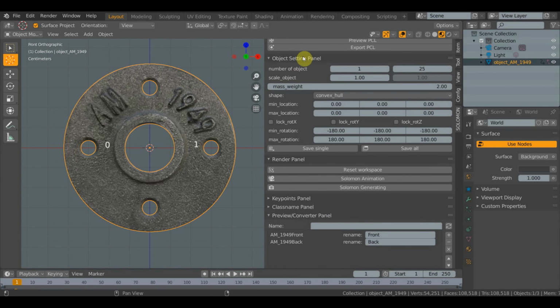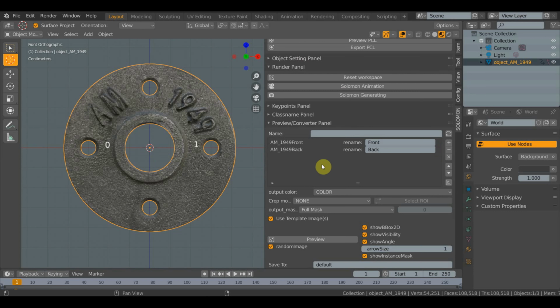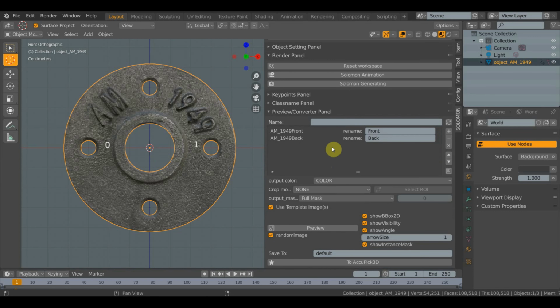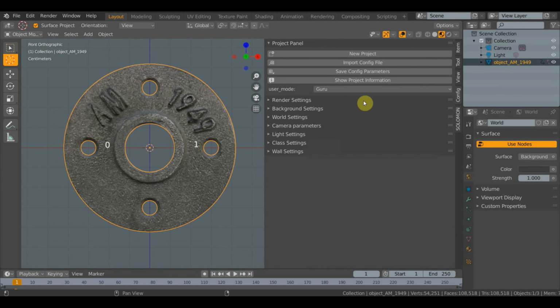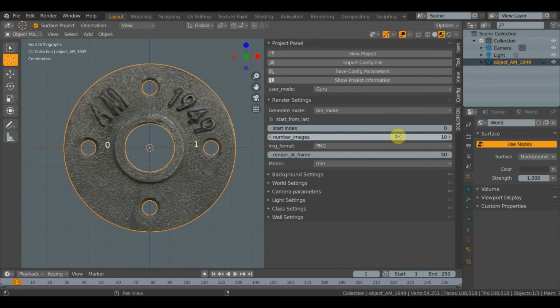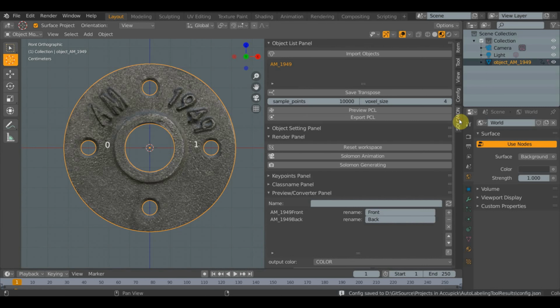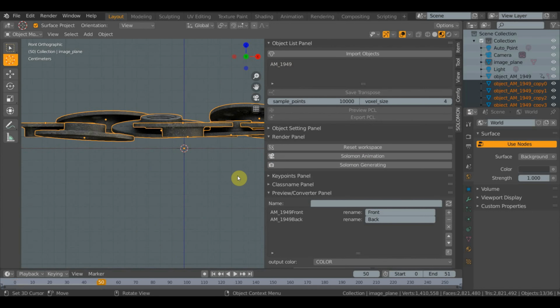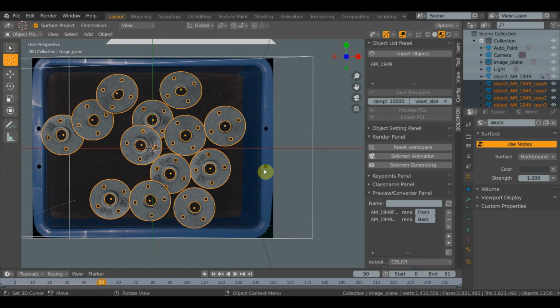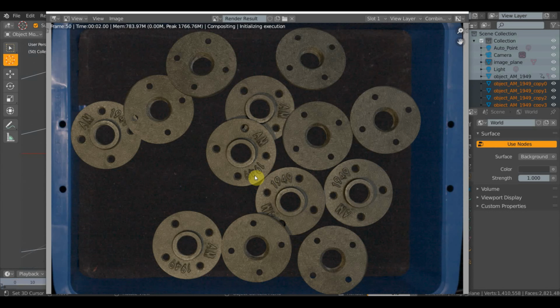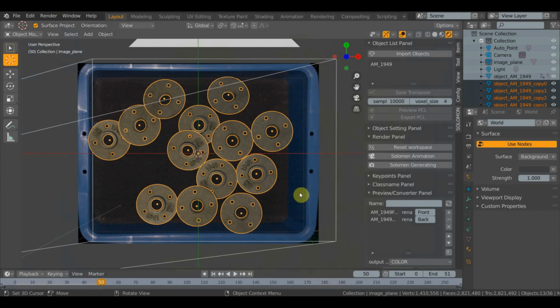Due to this being the first set of images we are going to create, I strongly suggest you start generating a small quantity of images with the objective to evaluate that the results are correct. That is why I am going to generate 10 images only. Also, don't forget to save the modifications recently applied to the project, and let's briefly check with one more simulation that the parameters recently determined have been saved correctly. Yes, it is correct. We have more quantity of objects inside the bin. Also, if I check the influence of the light, it should be also fine.